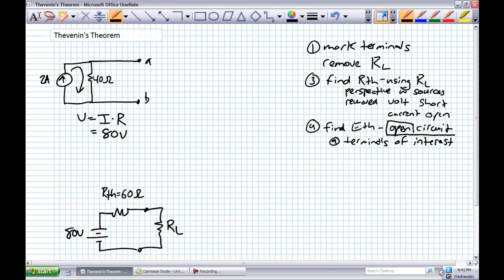Still don't believe me? Again, I challenge you to a rematch of the race. You got to use our original circuit. 20 ohms. RL. And let's say RL is 100 ohms. Okay, let's figure out what the IL, VL are for a 100 ohm resistor. Get ready, get set, go.